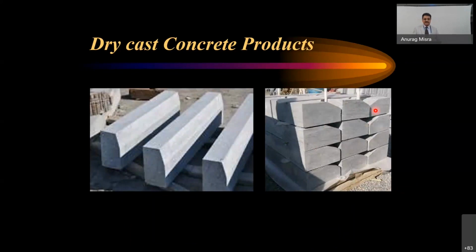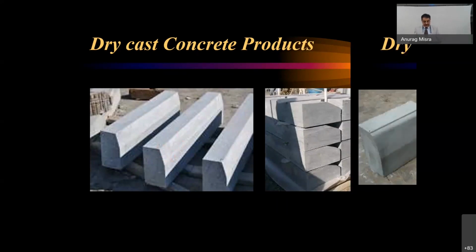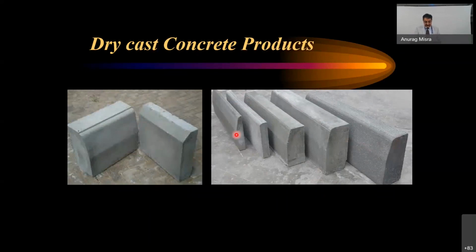These days on highways, there is a huge requirement which you cannot achieve the normal way. And cast in situ has limitations, because the ultimate strength achieved with that technology is only 15-20. If you do that, the deterioration of that concrete on roads goes very fast. Whereas these precast ones could be M30-40, which could be used for longer periods.